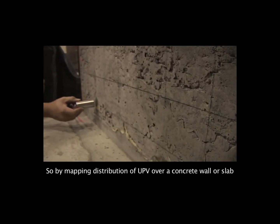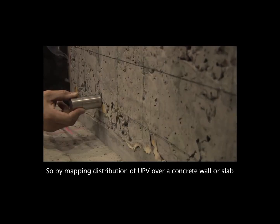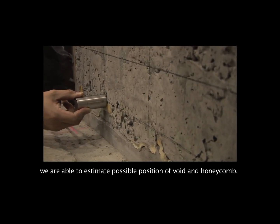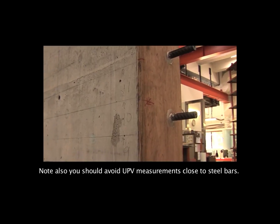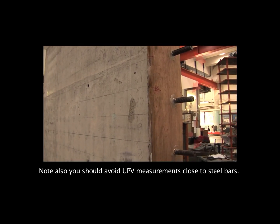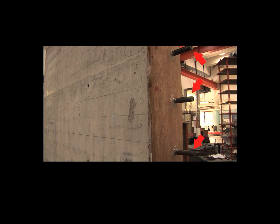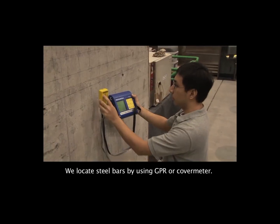So by mapping distribution of UPV over a concrete wall or slab, we are able to estimate possible position of void and honeycomb. Note also you should avoid UPV measurements close to steel bars. We locate steel bars by using GPR or cover meter.